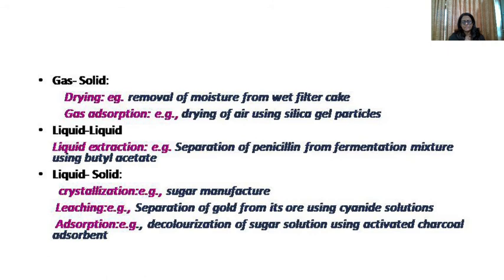Coming to applications, in sugar manufacture, the end product is a sugar solution, not solid sugar, so it's required that the sugar be in solid form. If you carry out the crystallization operation on the solution obtained, then the sugar comes out in the form of crystals. That is what is known as crystallization.